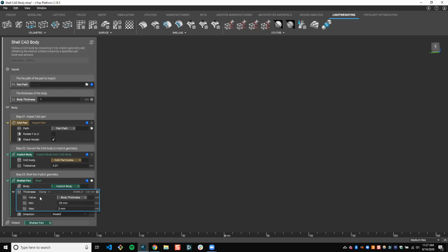So I've implemented this function under the hood that puts some guardrails in place. Perhaps there's a specific reason for this. Perhaps there are manufacturing tolerances that people need to abide by. Perhaps the minimum acceptable thickness for a 3D print is 0.25 millimeters, or the maximum acceptable thickness is 2 millimeters. And you want to make sure that if you share this workflow with others in your organization, they don't go below or above that value. Also, by putting this logic in place that acts as a guardrail for the end user, you always ensure that they have an output from this workflow that you've set up.